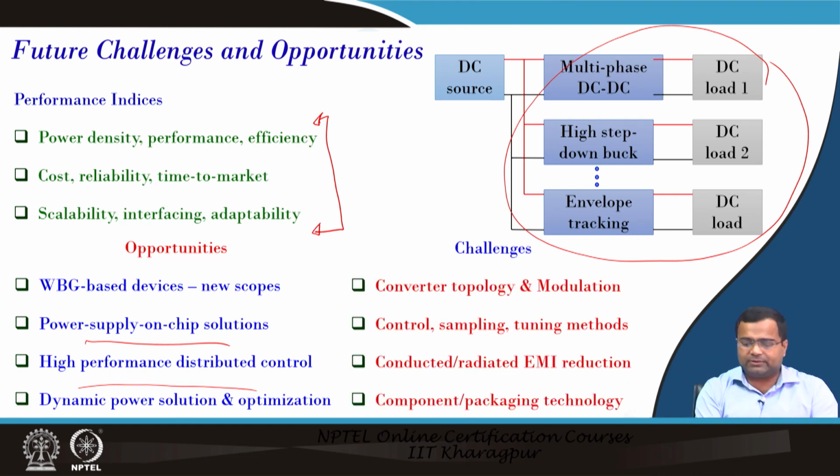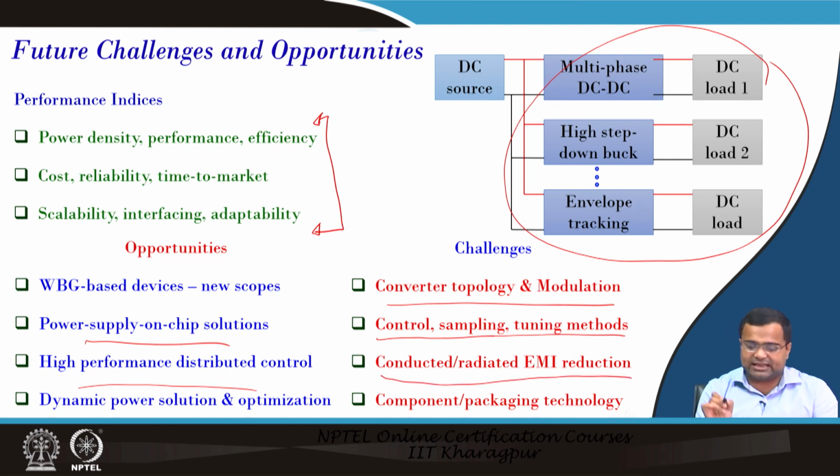But the challenges will be converter topology selection and modulation technique in the context of digital control. What is the right control technique? What are the sampling and tuning methods? Then how to reduce inductor and EMI aspects, where packaging technology will be helpful.